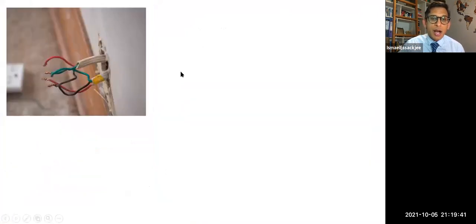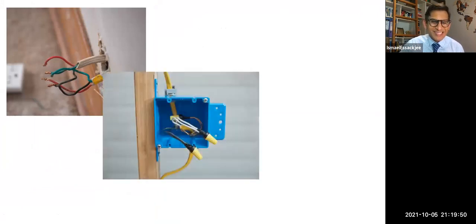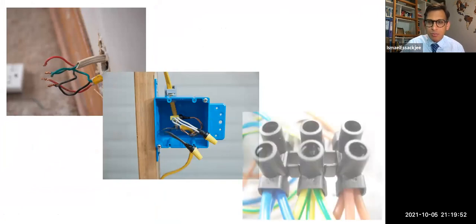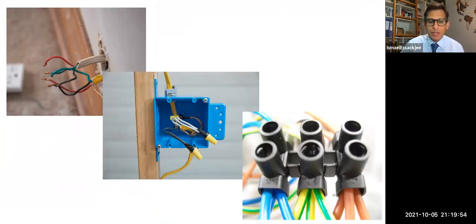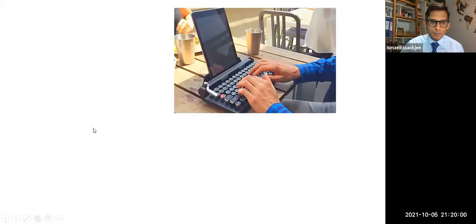We should be using appropriate connectors, this one as well. It's going to work, definitely. The system is going to work, but it is not safe, not recommended. This one is acceptable. I would prefer maybe using the common domino one, tight, and then you can insulate it with insulating tape later on for a proper connection.